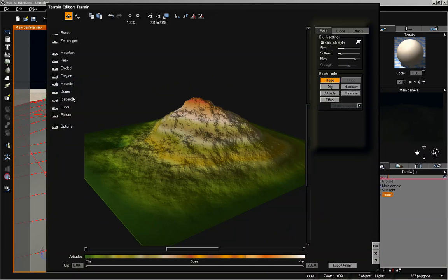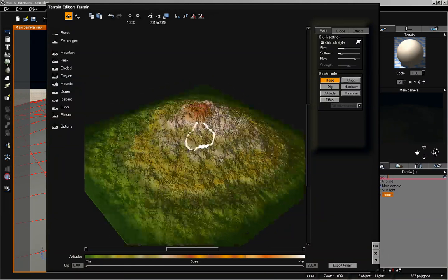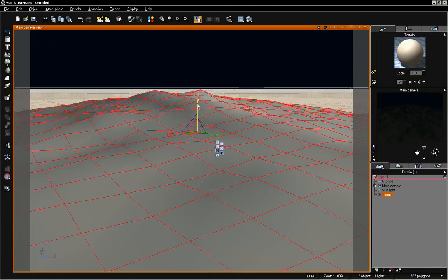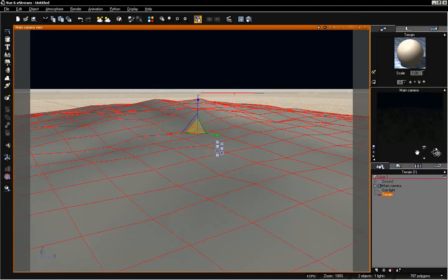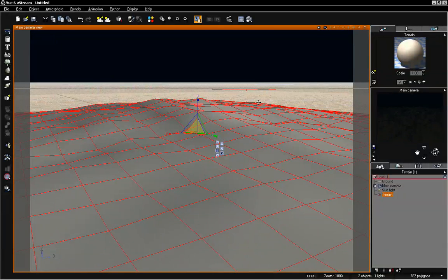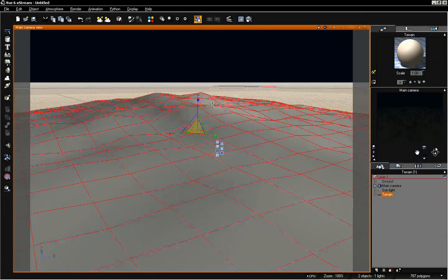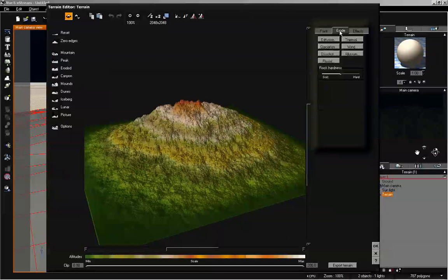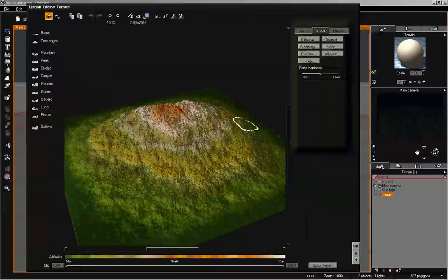So we can go over to the left and we're going to select mountain. And that will roughen it up a bit. And click OK. And now whether or not you want to have really smooth sand, you can modify that. But we can see right now with the mountain, we have more of a rocky surface. So I'll right mouse click, go to Edit Object, and if we want we can go to our road settings,